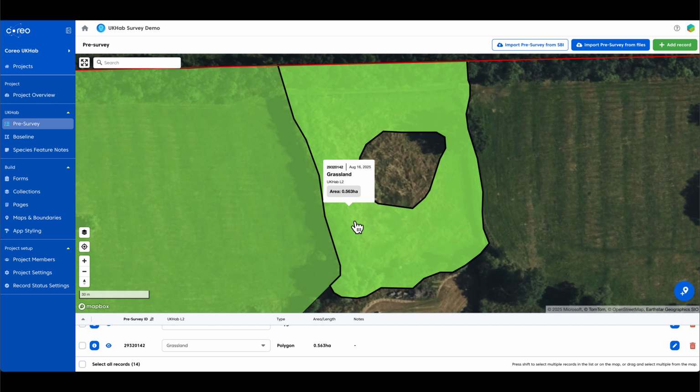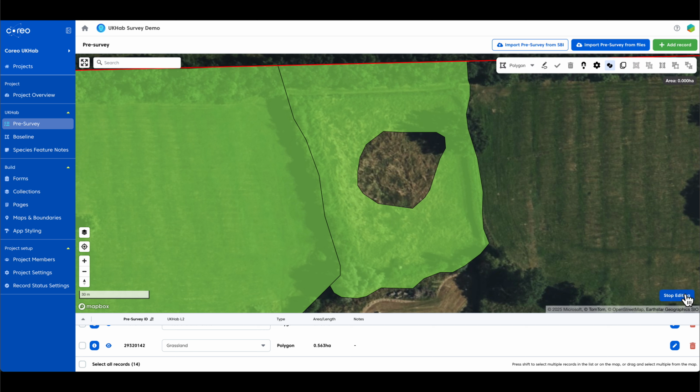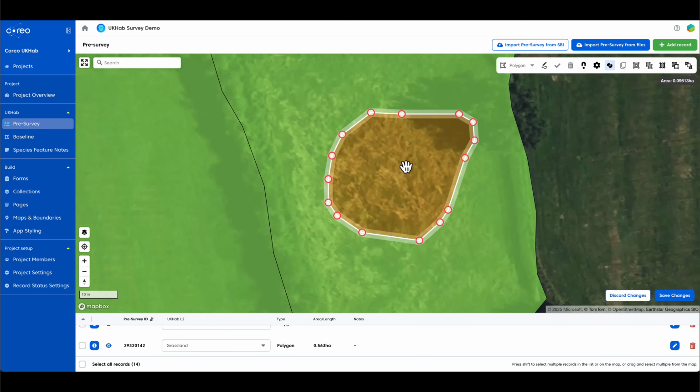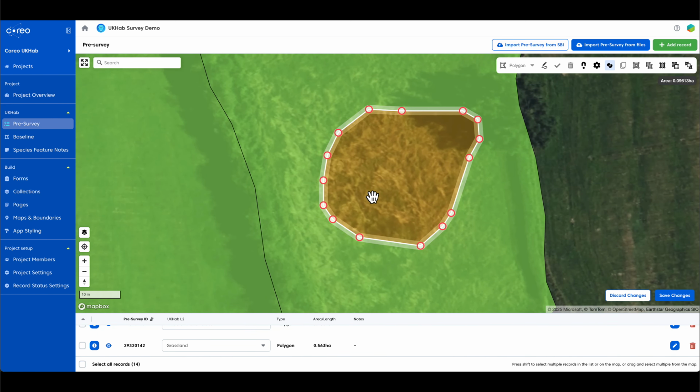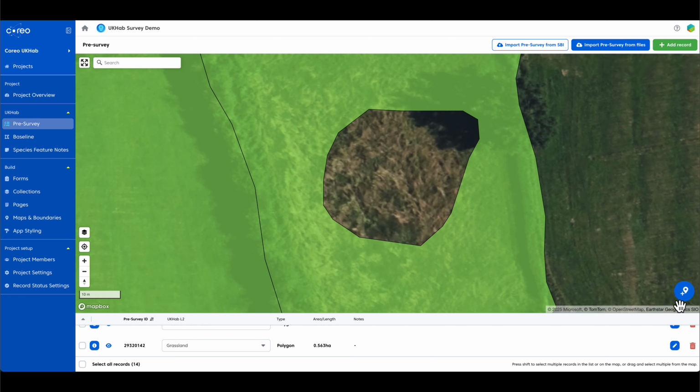So now I want to select this, let's call it a pond, that I've cut out of this parent geometry. I'm just going to go back, click on the plus symbol, bottom right hand corner, make sure that polygon is selected, reselect the use mouse option. The no overlap is selected already, but just double check that. I'm just going to loop around that very quickly, and that tool will then very neatly capture that inner ring for me. Click on Save Changes.